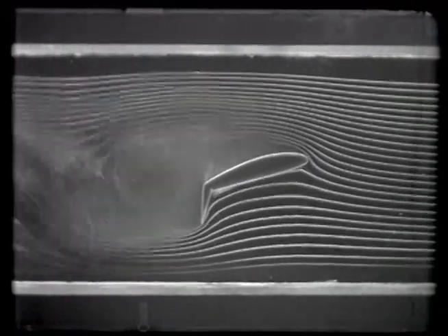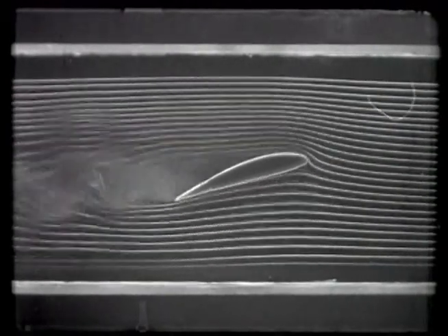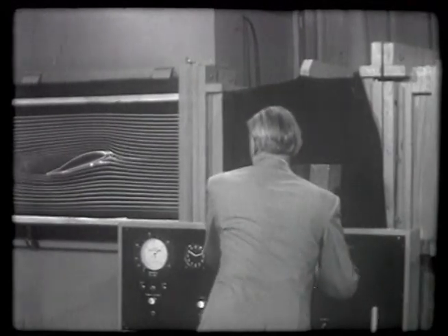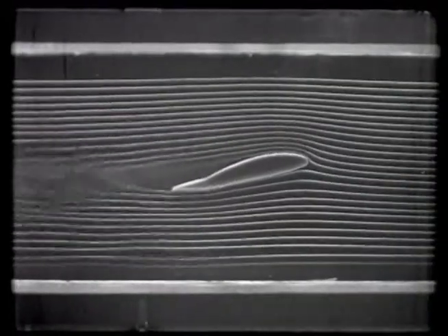Then the airfoil doesn't take it anymore, and the wing as such stalls out, which is quite dangerous, especially if this flap, for instance, is on the outer part of the wing, and you put one flap down and the other one up, and then this one, which you want to get up, stalls out and comes down, and, well, you know what happens then, huh? You call it timber. Anyhow, how can we change this? Or what can we do to prevent the stall under such conditions?